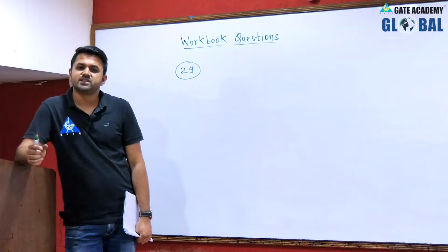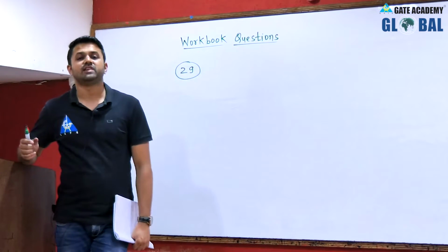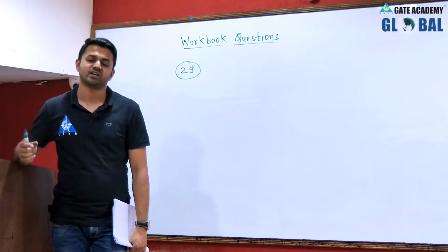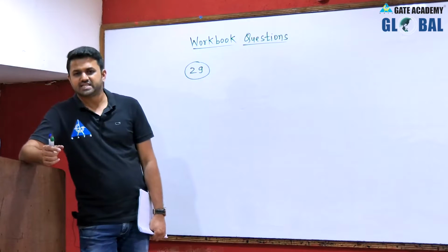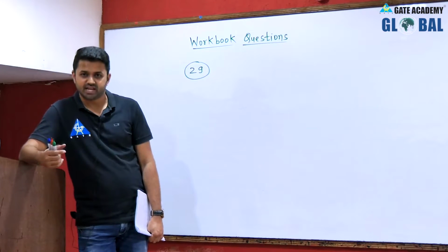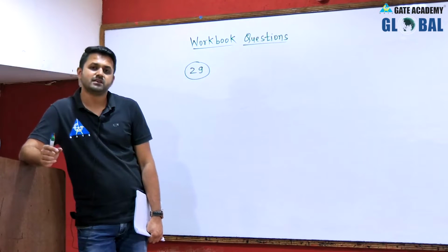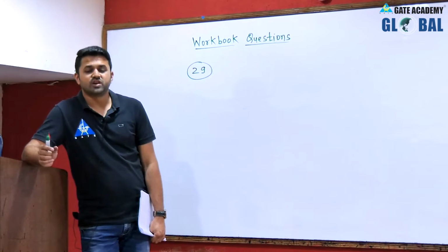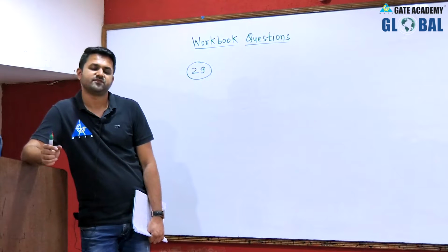Okay, so I have done this workout, and that's why I am able to say that we will get the same result which we got in case of the square law modulator. So I am not deriving it again, because the condition is very clear, and it is clearly mentioned that the condition for the carrier frequency is not even equal to 5 f_m, it is much greater than 5 f_m.